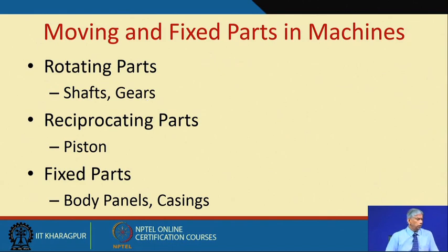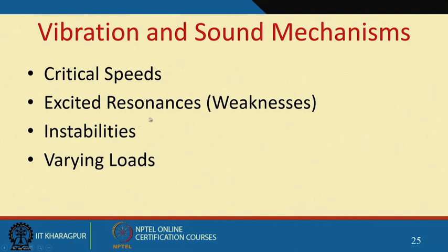So, we will focus subsequently on stationary signals and non-stationary signals. As you know, in any machine there are moving and fixed parts, rotating parts, reciprocating parts. All of these parts, when they rotate, are responsible for generating signals which vary with time, and it is these time varying signals which we have to analyze in the time domain, in the frequency domain, and in the time frequency domain to find out what the possible faults in the systems are.